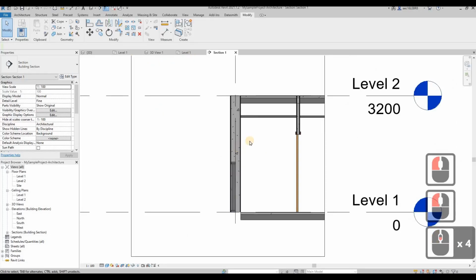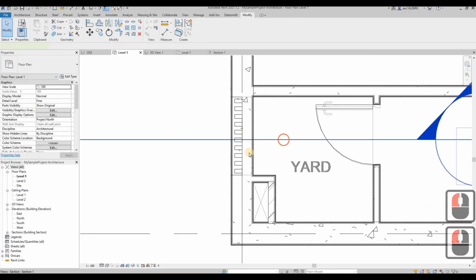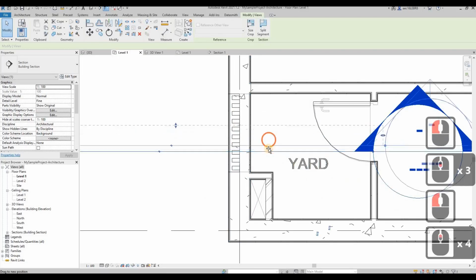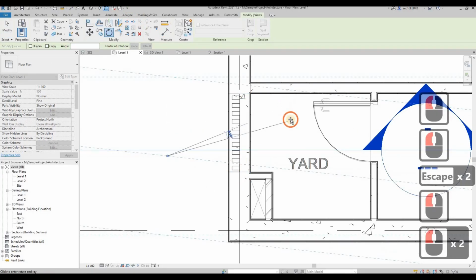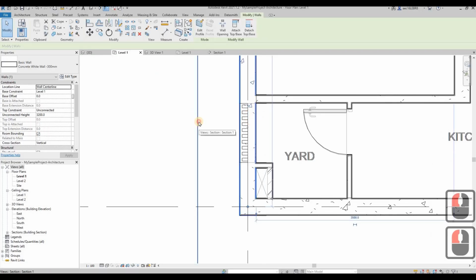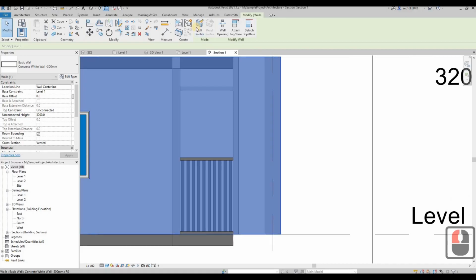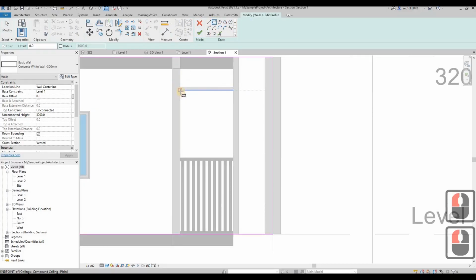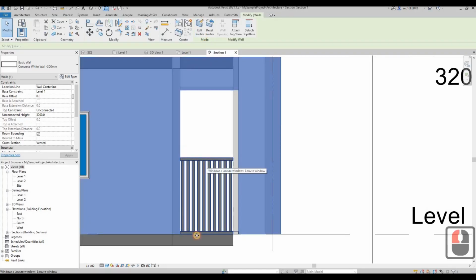Okay, so let's see how I can adjust my height. We go to this Level 1 again. I'm going to create one wall opening here, a 1 meter wall opening. Rotate this section view. I'm going to do this at this elevation. Go to view, then I'm going to cut the opening here. So edit the wall profile, then cut this opening from here until here. Then let's leave some curb over here to prevent water going into the house later. Click finish, then this is your Louvre opening.